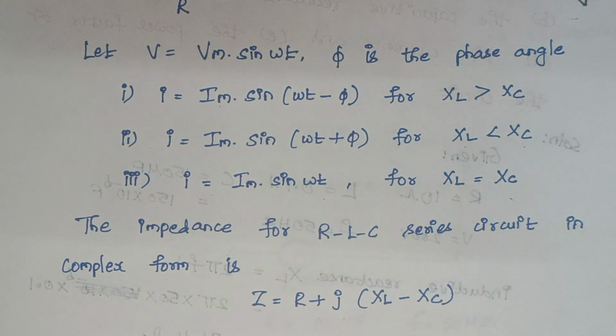Here in this case, we are having three elements which are connected in series, right? So even though we are having these three elements, the circuit can either behave as a RL circuit or an RC circuit or a purely resistive circuit, right? The dominant factor plays a main role. That is, when inductance is more predominant, then it acts as an RL circuit. When capacitance is more predominant, it acts as an RC circuit. When both the value of XL and XC are equal, then it acts as a resistive circuit, right? So keep these things in your mind.